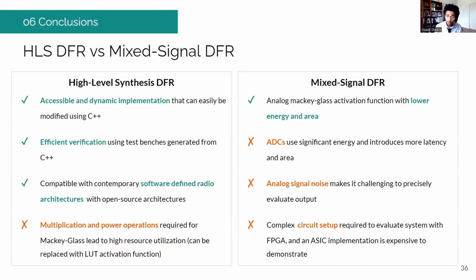So the high-level synthesis approach, which we just demonstrated, is very accessible, and we can easily modify the logic so that this can be adapted for a variety of different applications. It's very easy to test this, since the C++ code is able to not only generate the synthesizable logic, but it's also able to generate a test bench that can be run in ModelSim to verify that it works okay with the hardware implementation. Furthermore, actually implementing this in a software-defined radio to record the performance and test it in real time is very easy, since all of this is happening within the FPGA itself.